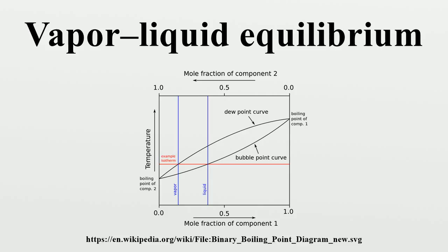Large-scale industrial distillation is rarely undertaken if the relative volatility is less than 1.05, with the volatile component being i and the less volatile component being j. K values are widely used in the design calculations of continuous distillation columns for distilling multi-component mixtures.